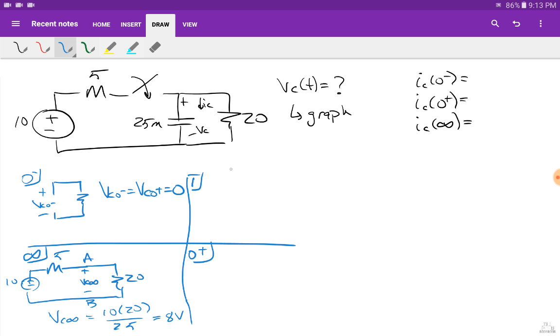So I'll come up here, I short my voltage, and I short it because I'm turning it off. Turn off a voltage source, it turns into a short, all right? And I label where the capacitor and or inductor is, A B, all right, because that's what we're trying to find the resistance around. This is my 20, this is my 5. If you're paying attention, this 20 and this 5 are not in series. I got to go between A and B. Between A and B is the 20, between A and B is the 5. So 20 and 5 are in parallel, okay?